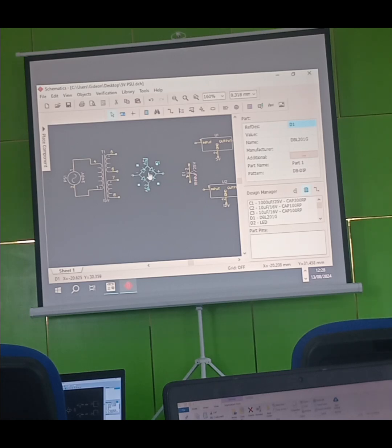But if you have a lower voltage at the input, like 12 volts, 12 volts minus 5 is 7. So 7 multiplied by 0.5. So the higher the voltage at the input, the more you are stressing that voltage regulator to step down. So it's better you have maybe +3 of the expected voltage going to the input. You get me now? Yes.